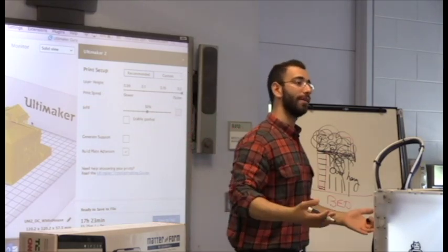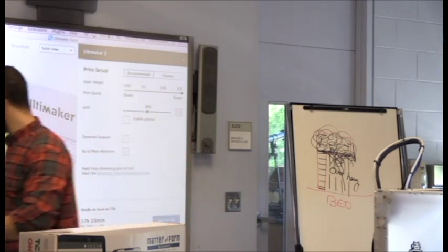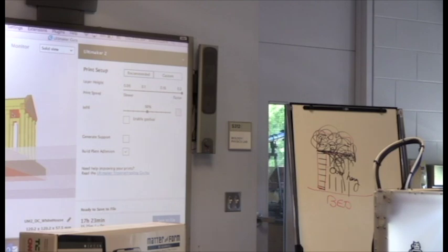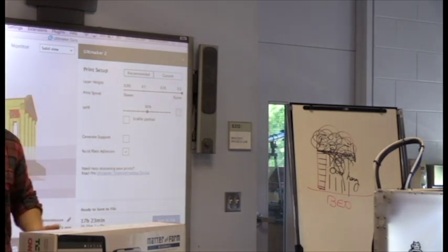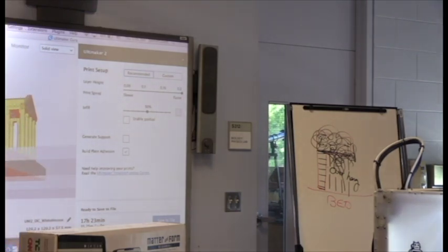And it's called support. When it reads the file, it sees overhang. Over here, you can see overhang whenever I move. You see anything under the bottom that has red on it? You see how it's yellow everywhere, but there's red? Anything that has overhang, whatever doesn't have support under it, is in red color. It recognizes where there's overhang. Does that make sense? Do you guys understand what the red part is?